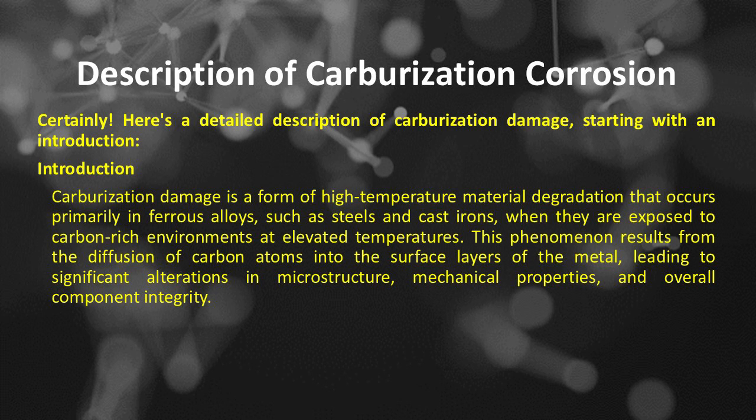Carburization damage is a form of high-temperature material degradation that occurs primarily in ferrous alloys, such as steels and cast irons, when they are exposed to carbon-rich environments at elevated temperatures. This phenomenon results from the diffusion of carbon atoms into the surface layers of the metal, leading to significant alterations in microstructure, mechanical properties, and overall component integrity.